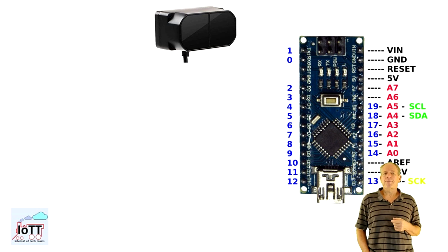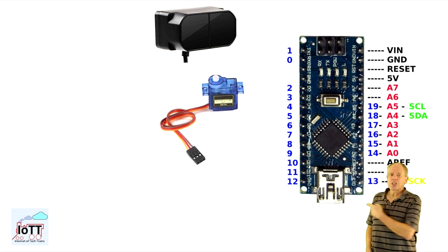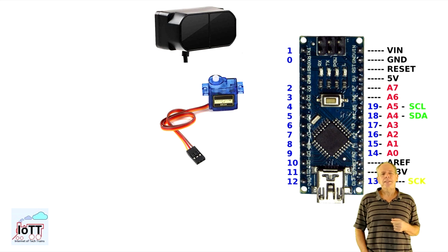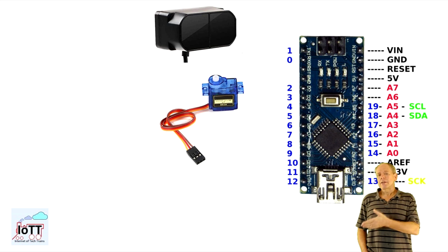We will see. An SG90 servo to mount the sensor on. The idea is to rotate the servo and point the sensor to various locations, then give each location a different block number, and therefore this will be a multi-block detector that can be configured in software. And by choosing what messages to send, it can act as a point or an area detector, actually both at the same time if needed.